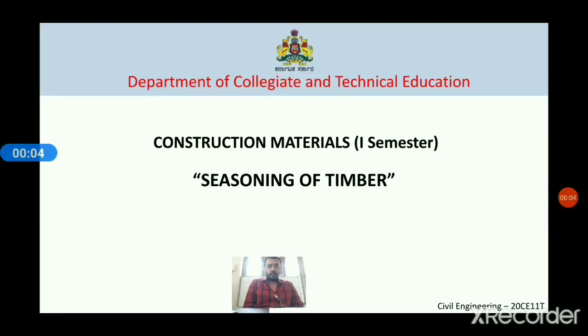Hello everyone, in this video we'll discuss what seasoning of timber is, whether it is really necessary, some of the objects, and also the methods of seasoning timber. Generally, freshly cut timber will be too wet for normal use and is unsuitable for engineering purposes. So seasoning is the process of reducing the moisture content, that means drying the timber, in order to prevent fermentation and decay and make it suitable for use.